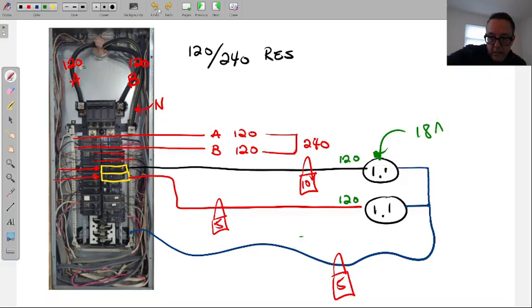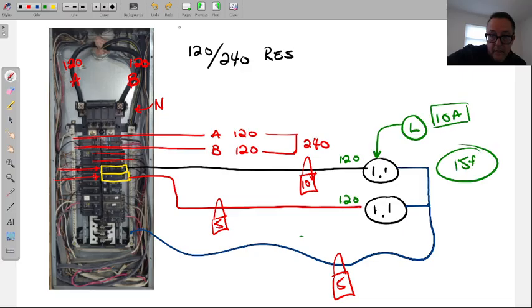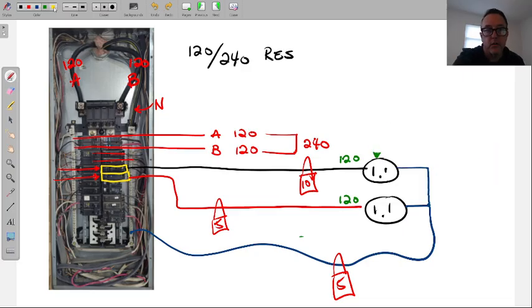But what you should understand is, don't even worry about the loads plugged in, the neutral is going to carry the unbalance of both. Or the unbalance between these two independent circuits, where you can plug whatever you want into this one and whatever into this one. They're independent of each other. So the neutral is now dealing with whatever is left over, the unbalance of the load.